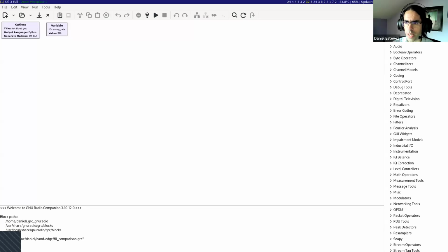And the second part, which should hopefully be after the break, will be about spectral analysis. So that means we have some signals, we compute a spectrum, and then in the spectrum, we hopefully should be able to detect the signals if they have enough signal to noise ratio. And for that, I will show you how to generate some simple types of signals in GNU Radio, such as narrowband signals or CW carriers, basically a constant tone of constant frequency and amplitude, and also wideband signals. So that is a signal which has some particular bandwidth to it and occupies some portion of the spectrum.